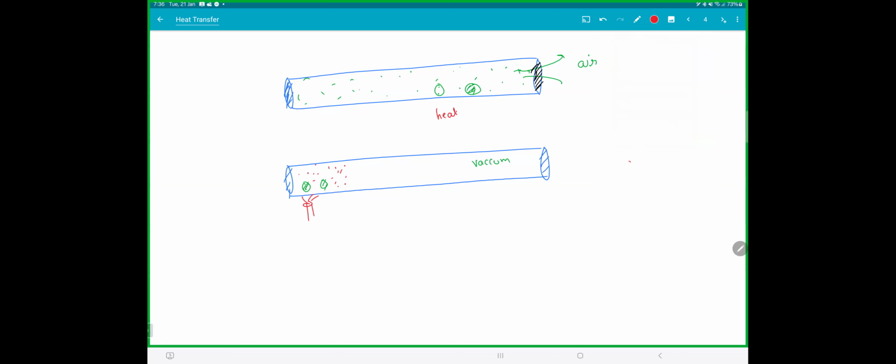But right side there is a vacuum now. So what will happen? The steam will rush from left to right. And suddenly the whole pipe, the heat got transferred, isn't it? You're getting why it is so fast? The moment you give little heat, it will vaporize, and the right side is a vacuum. The water vapor will rush from left to right, carrying all the heat.